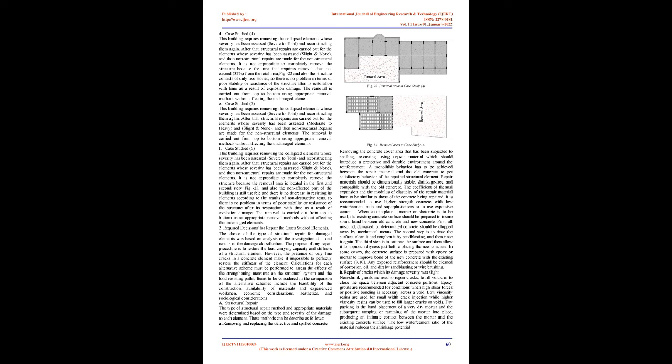F. Case studied 6. This building requires removing the collapsed elements whose severity has been assessed as severe to total, and reconstructing them again. After that, structural repairs are carried out for the elements whose severity has been assessed as slight and none, and then non-structural repairs are made for the non-structural elements.